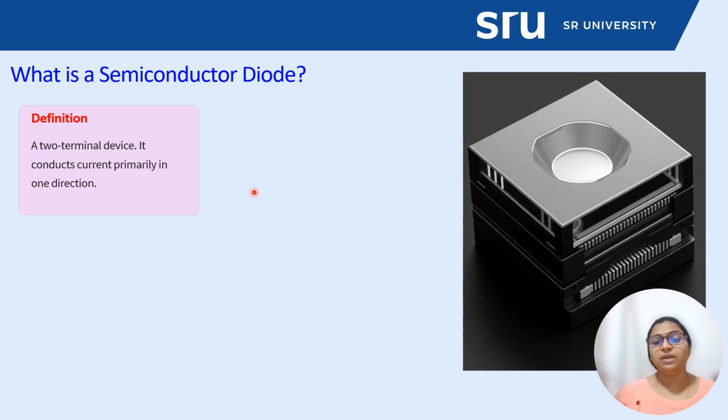Depending on the type of doping, as we have covered in detail in a previous lecture, let us briefly say n-type uses donor atoms. If we dope phosphorus in silicon, that means we are adding electrons. P-type semiconductors use acceptor atoms. If we dope boron in silicon, it will create holes.